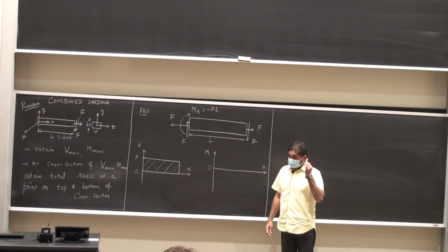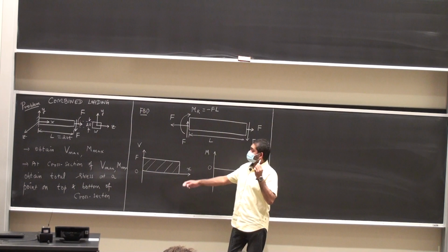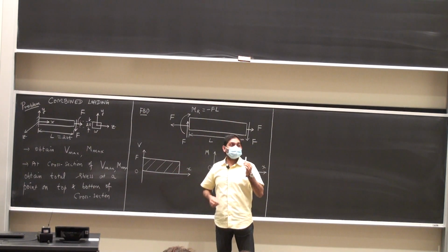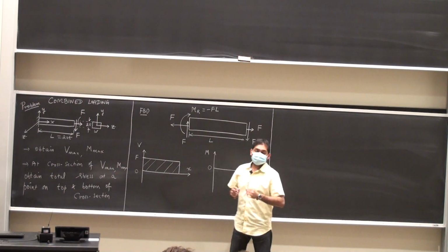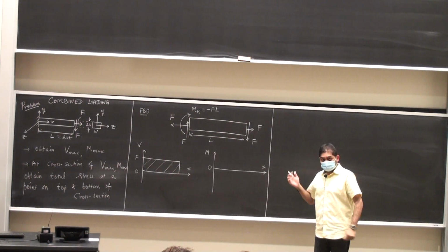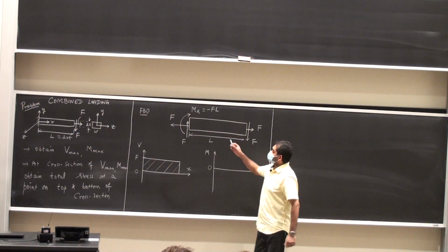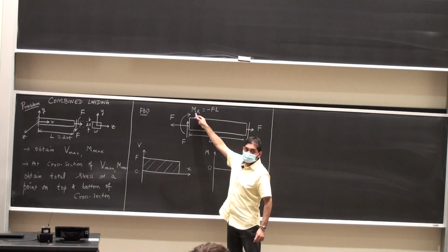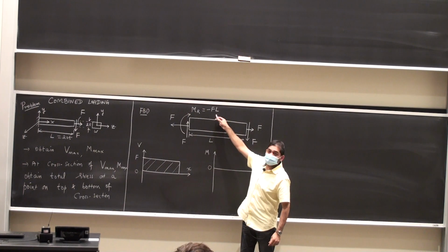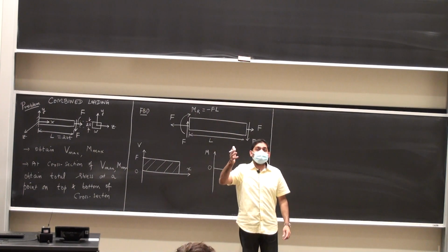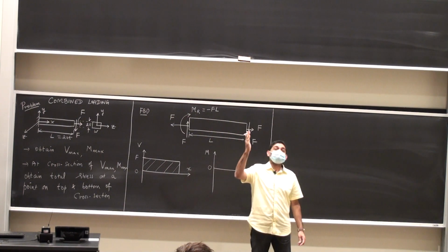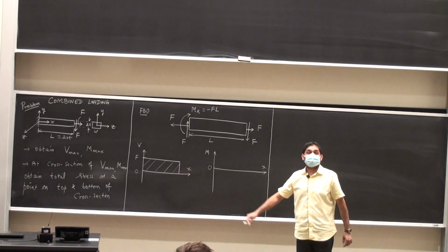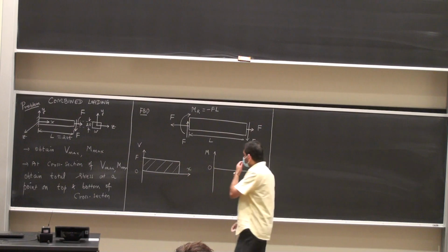Another dead giveaway is that the shear force is positive. So if I start off positive, I'm just going to keep climbing positive. You don't want that to happen, right? So you're going to come back to 0. But the right way to look at it is the following. So this is drawn clockwise, but it has a negative value. If I have a clockwise couple moment, it causes an upward jump in the bending moment diagram. But because its value is negative, I'm going to start at minus F times L. Okay, so I'm starting here.